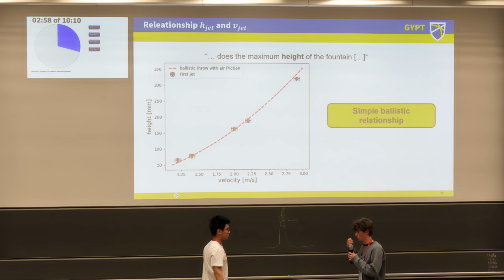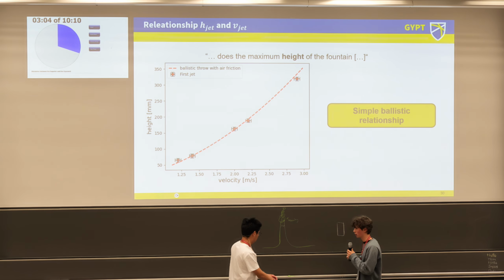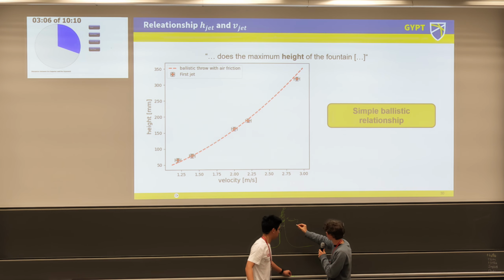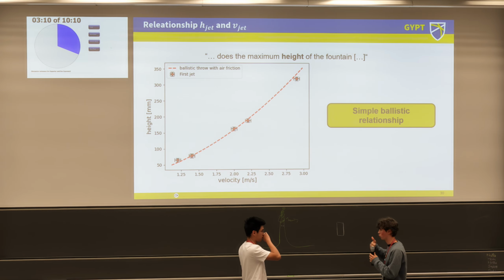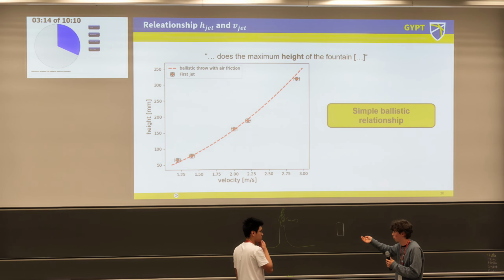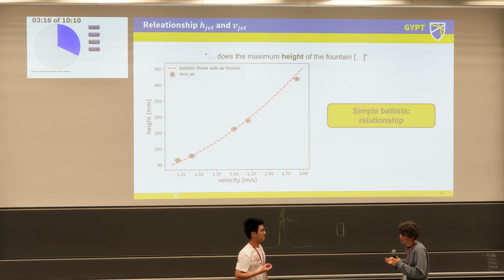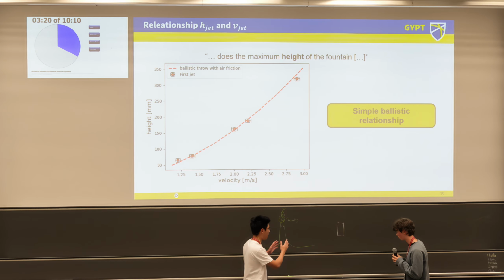And for this you would need a full CFD, because you can't approximate it to be a perfect cylinder, for example, which would simply be incorrect. To find the radius up here, which you would need for your surface tension and then your radial plateau, you would need a full CFD anyway, so then I could just model my whole problem using a full CFD. So I agree with the reporter on this.